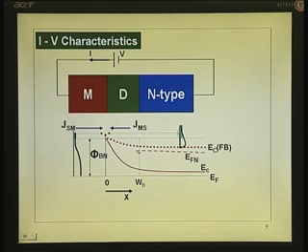You can see that this is less than the total area under the curve. So, it is less than the thermal equilibrium electron concentration. Over here, this shaded portion, those are the electrons which can cross the barrier, which can give rise to current JMS in this direction due to electron injection from here to here. Whether forward bias or reverse bias, this quantity is not changing because this phi Bn is not changing. All that happens is here. So, this will give rise to JMS, which we usually call J naught, whereas JSM is due to